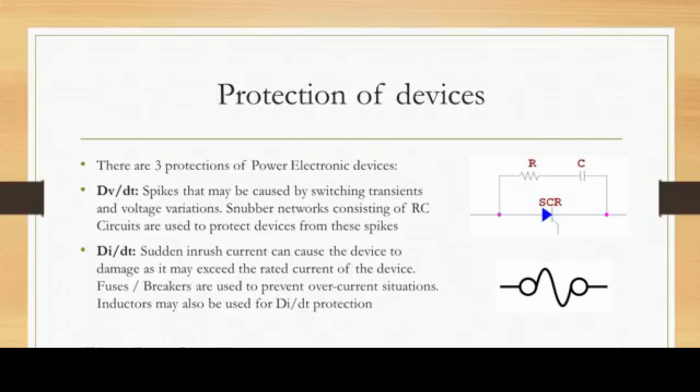The semiconductor devices may be protected by carefully choosing the locations of the fuses. However, the fuse manufacturers recommend placing a fuse in series with each device. When the fault current rises, the fuse temperature also rises, at which point the fuse melts and arcs are developed across the fuse.